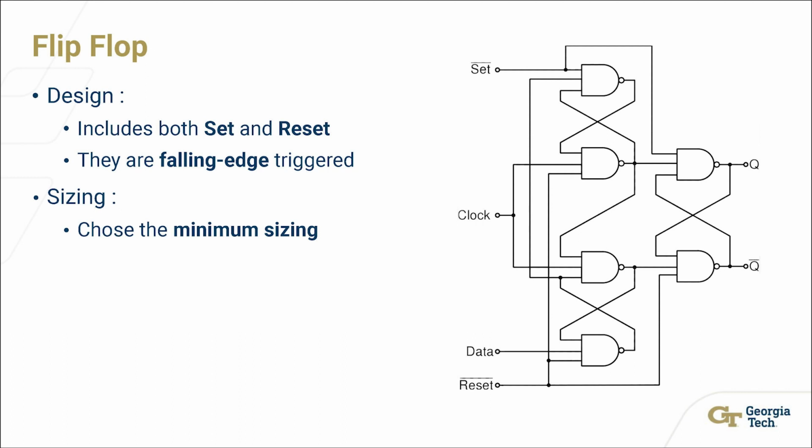And finally, using multiple NAND gates, we designed the flip-flop, which also includes both the set and reset operations, which are falling edge triggered. And the sizing of the flip-flop depends on the sizing of the NAND gate, which is the minimum sizing.